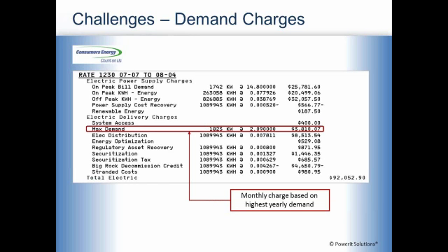In this case, you can see 1,823 kW at $2.09 per kW. Once you set the maximum demand charge, you live with that charge for the month you set it, plus the next 11 months before it goes down. So for facilities that are operating off-peak, you may have that maximum demand charge, and you are paying a penalty even though you don't realize it.